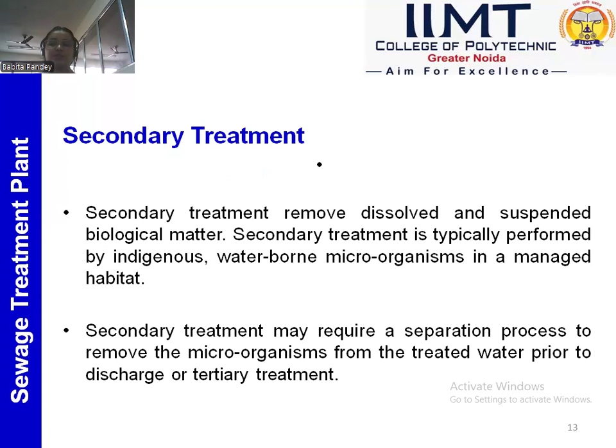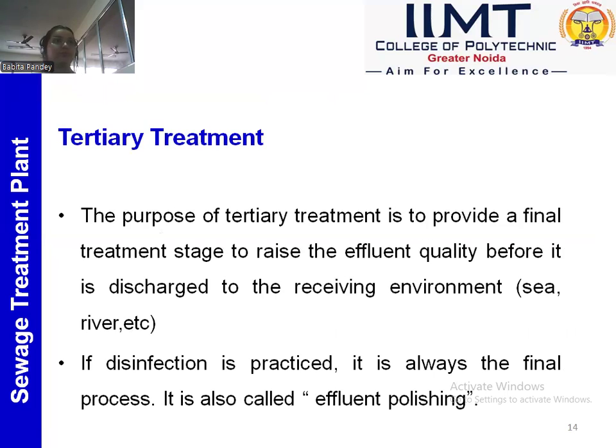Now coming to the secondary treatment. Secondary treatment removes dissolved and suspended biological matter. Okay. Secondary treatment is typically performed by indigenous waterborne microorganisms in a managed habitat. Secondary treatment may require a separation process to remove the microorganisms from the treated water prior to discharge or tertiary treatment.